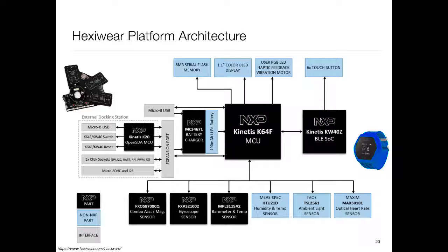If I have an accelerometer sitting on the table, what would be the readings? G. Yeah, 0, 0, and whatever, depending on the axis. One of them would be G. So don't forget, gravity is also there. The magnetometer senses, obviously, Earth's magnetic field, but other things also affect it: any large ferromagnetic mass, speakers, and in a typical lab setting a lot of electrical equipment, and also AC current flow.